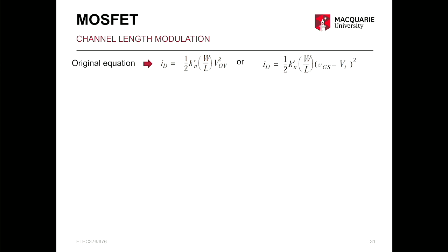Understand how, because the distance between the two terminals is constant, it cannot change. So when the length is reduced, how does the current continue to flow? Yeah, that is because to reduce the channel length, you need to apply more and more voltage, right? The voltage is increased. That is why the length is reducing. And at some point, it's actually tunneling through that point.